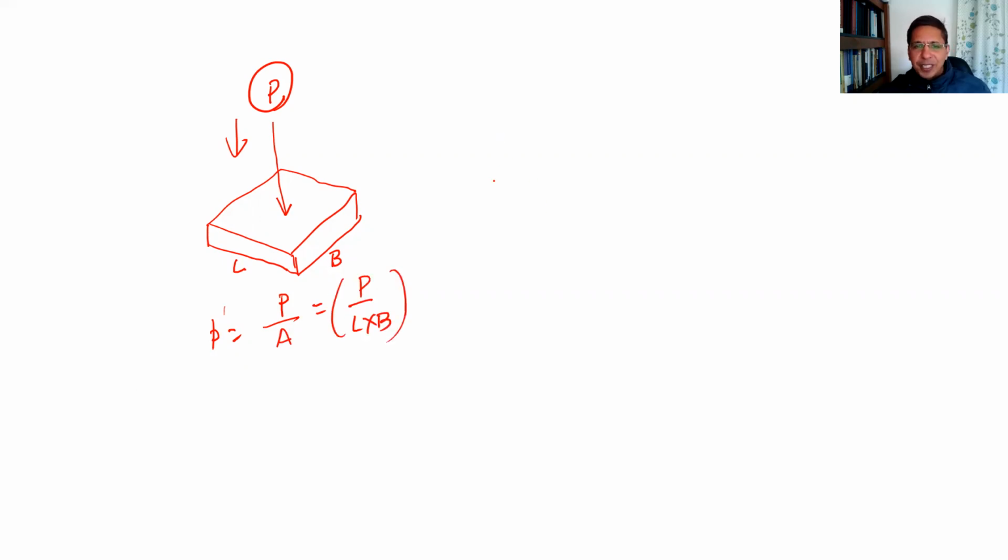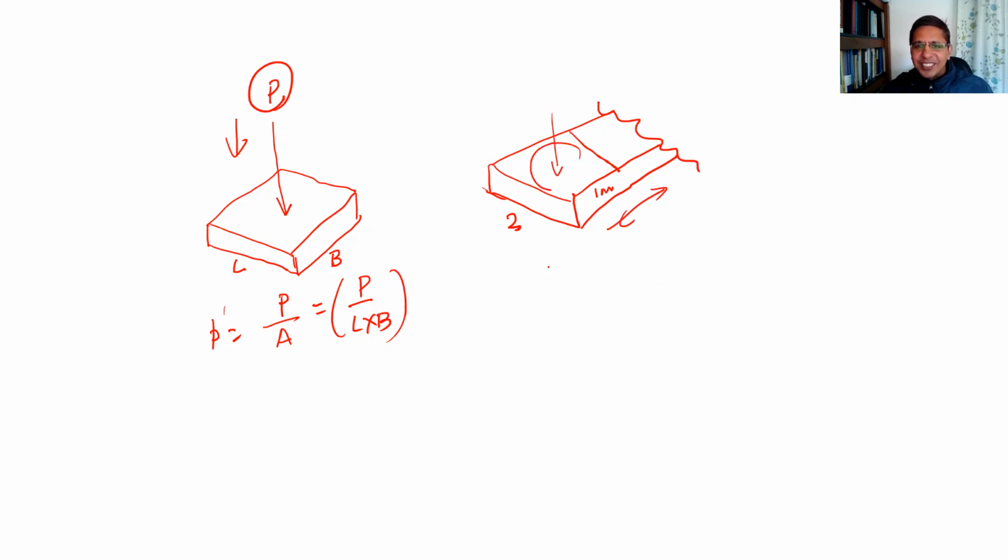If it is strip footing, what does that mean? Can I draw now? There you go. So now this side keeps going. That side, right? So this is continuous. Strip footing means this side we know is 2 meters, but because we cannot go continuous, how long do you calculate the area? So we just took 1 unit length of area. We calculated for this part only. So area equals 2 times 1. Did I make it clear now?